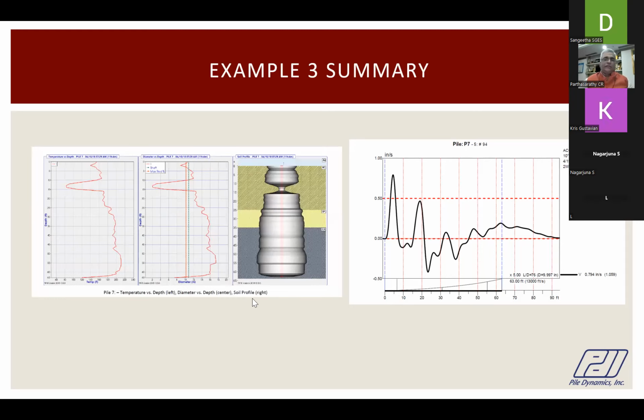So when you do a tip testing as well, you see a localized cooler zone at the same level, close to the pile top around 15 feet. This is same as indicated by your tip and the PIT as well. So both PIT and tip identify major defects. Thank you. Fantastic, guys.